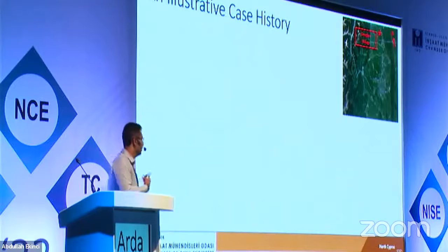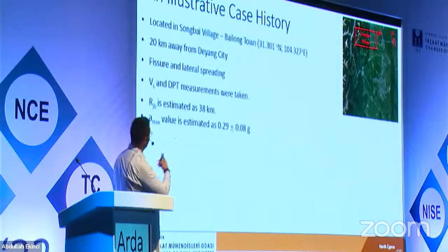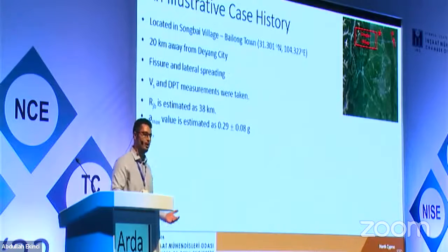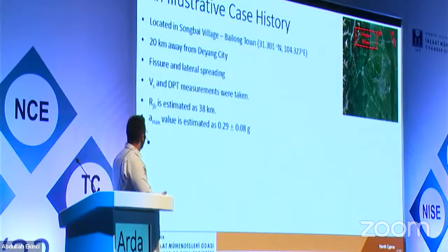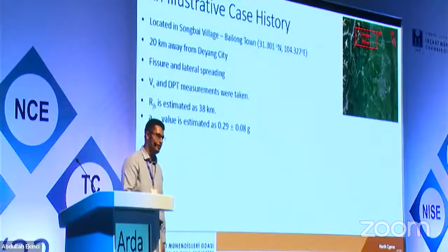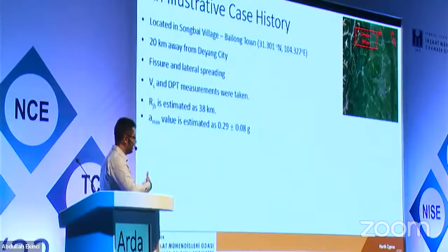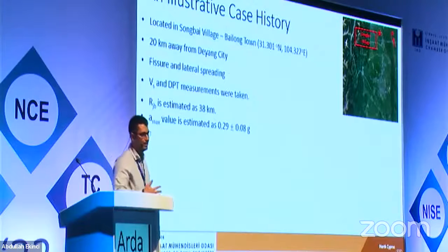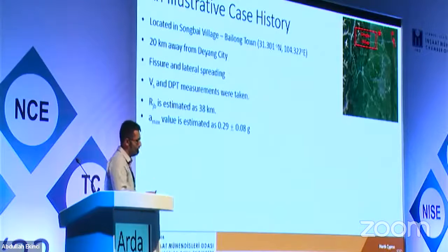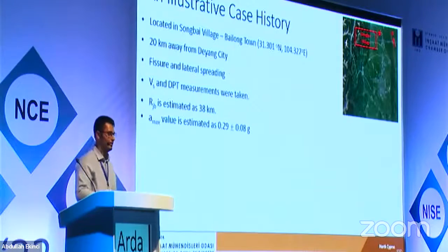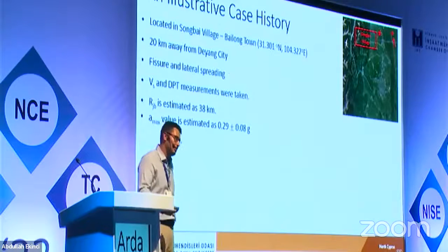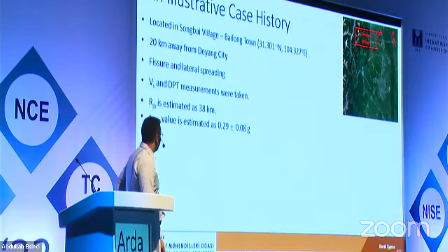I selected Songbai village. You can see the location there, and it is 20 kilometers from Dayan city, which is one of the biggest cities there. And here, fissures and lateral spreading are seen in the site. However, when I examined, most of the sites did not have excessive settlement problems for gravels, and I thought that excessive settlements might not be relevant to gravels. That might actually raise a question.